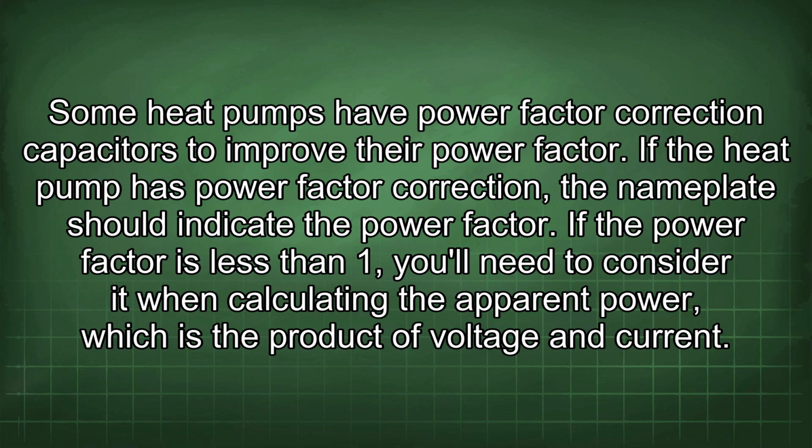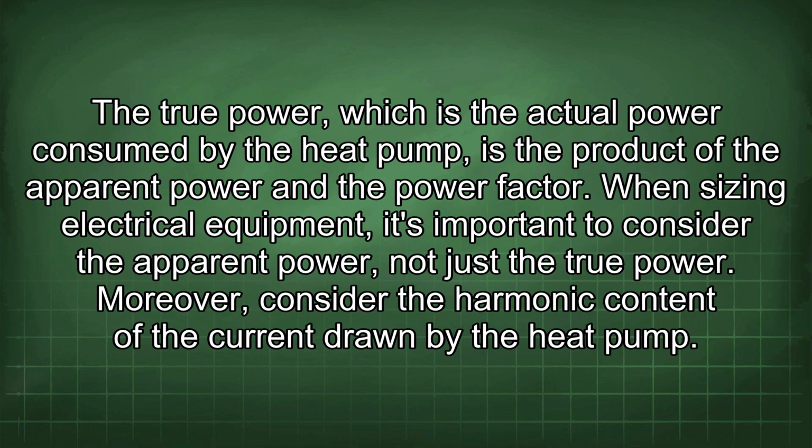If the power factor is less than 1, you'll need to consider it when calculating the apparent power, which is the product of voltage and current. The true power, which is the actual power consumed by the heat pump, is the product of the apparent power and the power factor. When sizing electrical equipment, it's important to consider the apparent power, not just the true power.